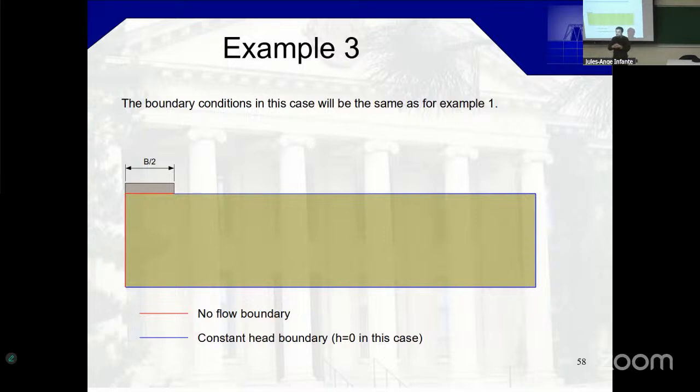Problems involving consolidation or flow properties, and so the water can go in two ways. So the formula will be a bit different. Excuse me, is this the same principle that GeoStudio used in the analysis? Yeah, yes. The only difference is that we are doing finite difference. They use finite element, which is a different way of setting up your matrices, okay? In the end, when you go to steady state, mathematically, in the code, it ends up looking very similar, to be honest. What changes the most is the coordinates.